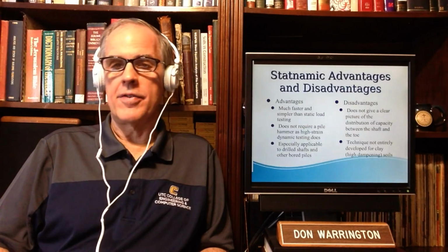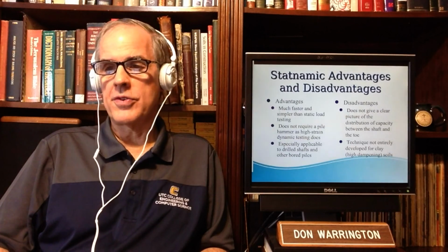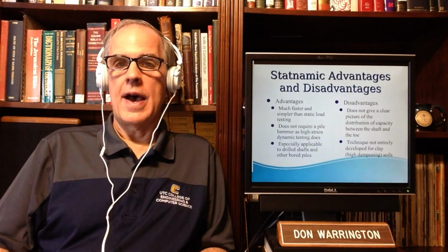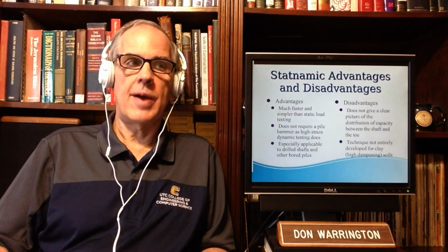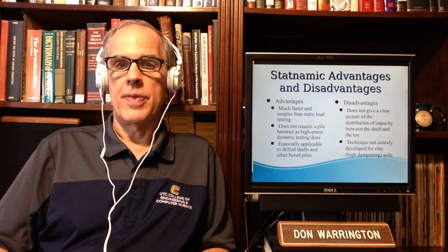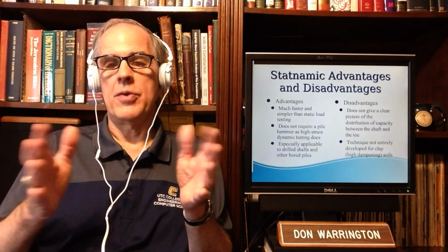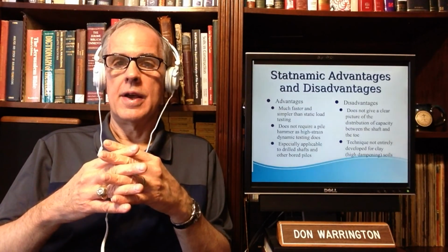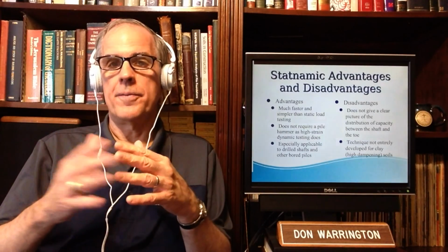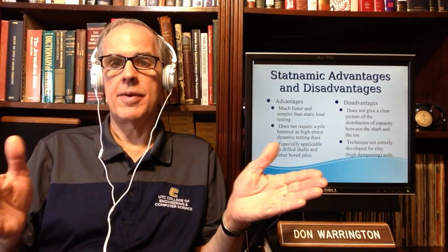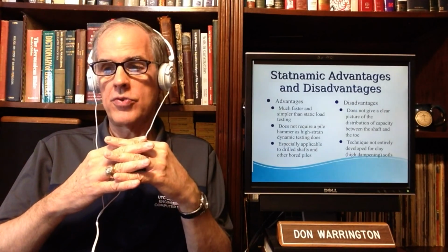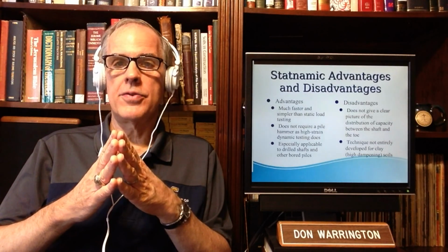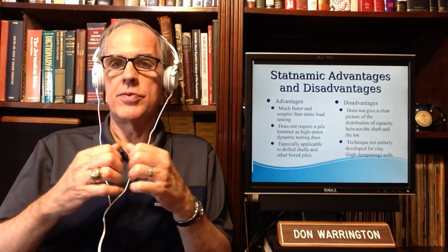And it's not entirely developed, although there have been continual advances with Statnamic testing for clay, high damping soils. I would strongly suggest it's an excellent method. It has its limitations like any other method, but it combines characteristics of both static testing and dynamic testing into one. And it can, of course, be used for lateral loads, as I mentioned. It can be used to simulate impact loads as well, particularly in lateral loads.